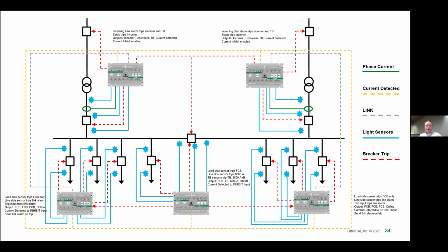Now, I'm not going to go through the mechanics of this in detail, but when you look at how the arc flash relays are applied, this is something that can be quite flexible to all types of systems, depending however the customer would like to have that installed. So, this system here is showing a tiebreaker with 2 incomers on the bus, and arc flash relays, as I mentioned, are nice because they're flexible.